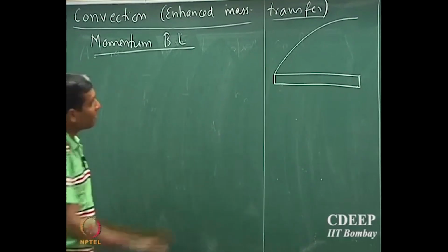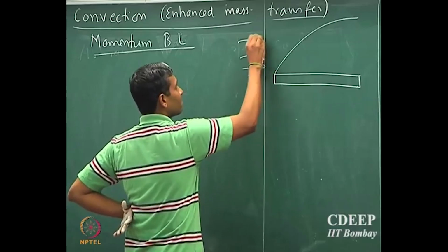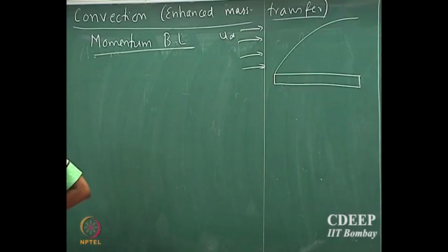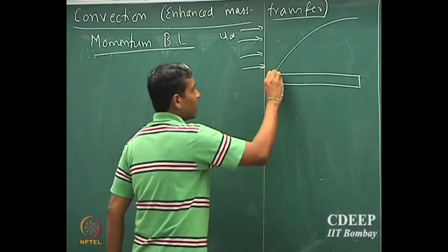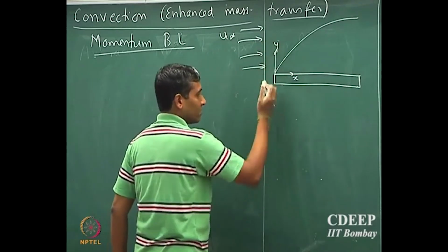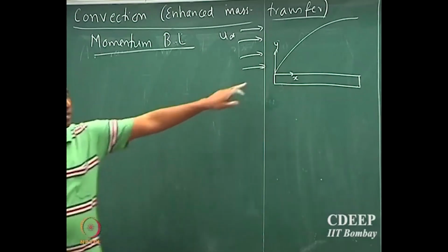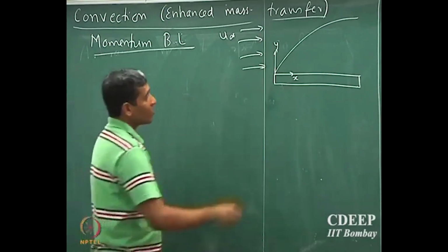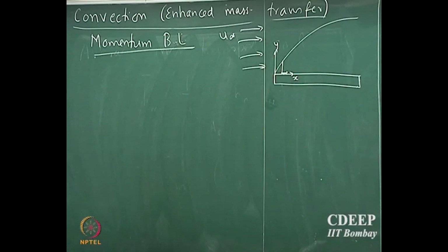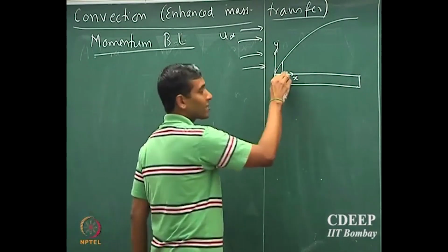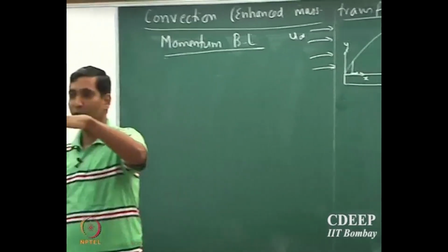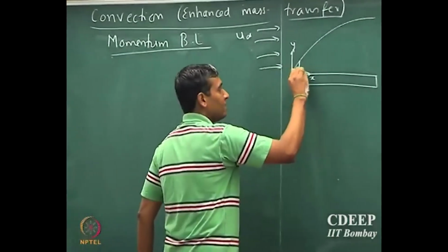boundary layer. So what happens is that the fluid which is coming past this object, so let us say the free stream velocity is u infinity, okay. So suddenly at y equal to 0 and x equal to 0, the fluid will suddenly come to rest at this location here, okay. But because of continuity, note that it is a continuous stream, okay. So the fluid which has come to rest here is now going to retard the fluid particles which are actually flowing above it. Supposing we take a fluid particle here, okay.